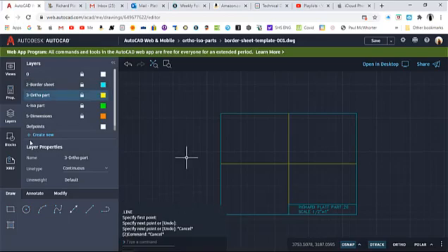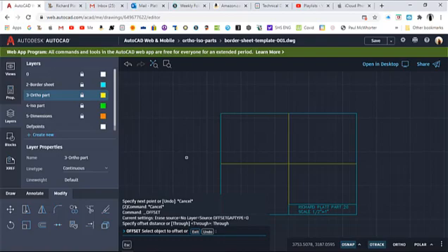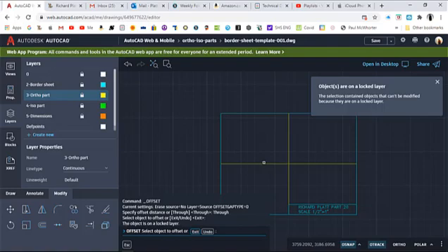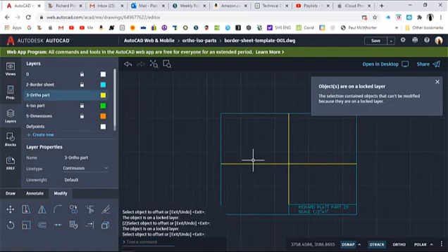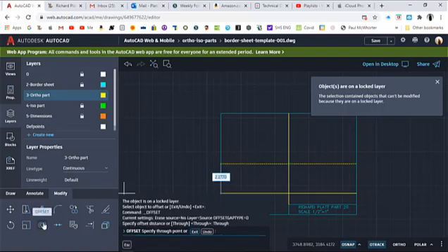And now what I'm going to do is go to find our offset command. It says select an object to offset, so let's see here, find this layer here. Is that layer? Oh, I actually unlocked the layer, my bad. Unlock that. Okay, let's try this again. Select the one I'm going to offset. There it is. We'll hit offset, and we're going to offset this 1 inch.